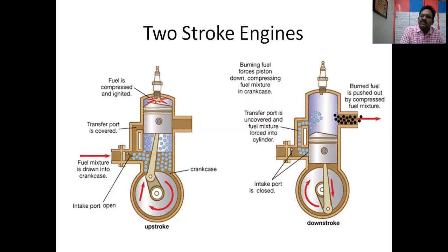Two things happen. One is the exhaust port will be opened and burned gases will be sent outside, and the transfer port will be opened, therefore fresh air will come. That means simultaneously into the combustion chamber, fresh charge will come and the burned gases will go out. That's why, in order not to mix this fresh air with the exhaust gases, a deflector will be provided. So it will go here, and it will in fact push these exhaust gases out of the chamber. And it will be repeated.